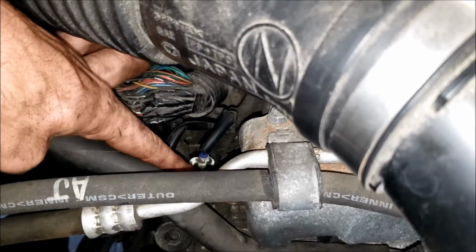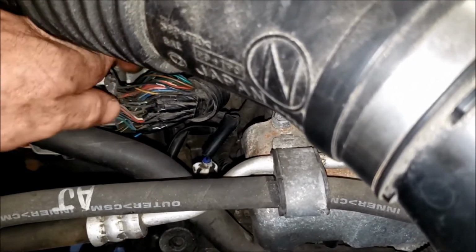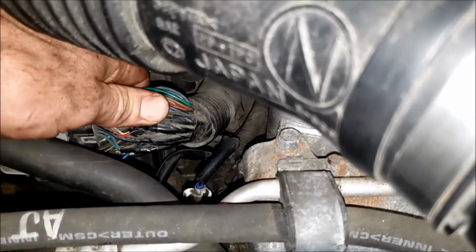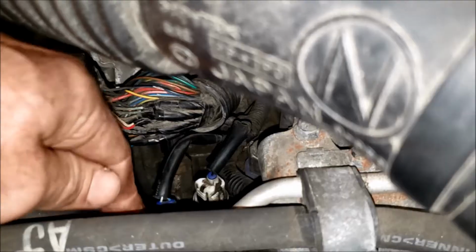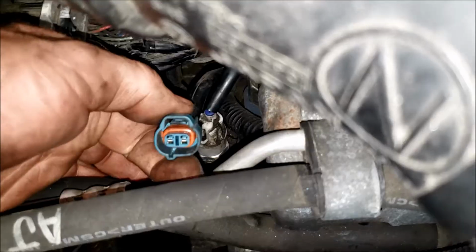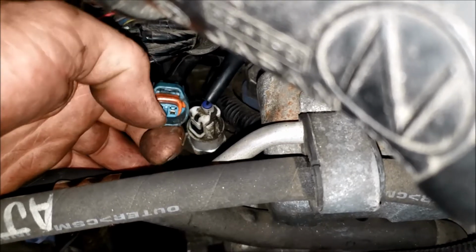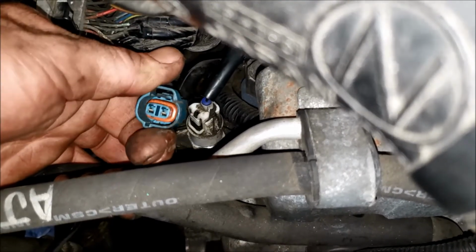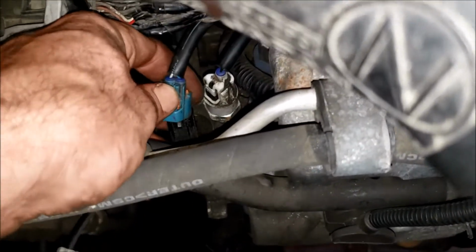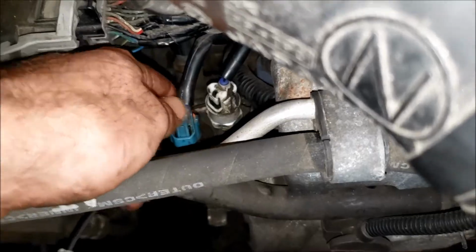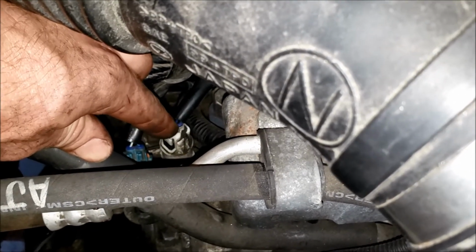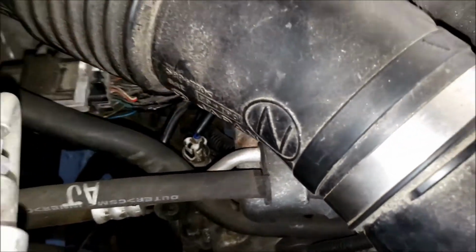Now, if you found no issue with your oil pressure switch, solenoid, or motor oil, I'd have to say the next step is going to be checking all your wires for any chafing or broken wires, especially the harnesses that go to the solenoid and the pressure switch. You'd also want to pop these pigtails off and check inside, make sure they're not corroded, bent up, or mangled, and that your terminal pins are straight and in there as well. Just obvious stuff. So I think it goes without saying that these oil pressure switches are a very common failure on the Subarus and their VVT system.